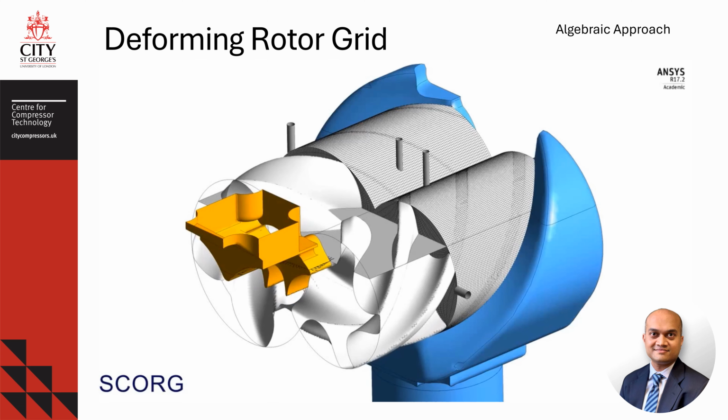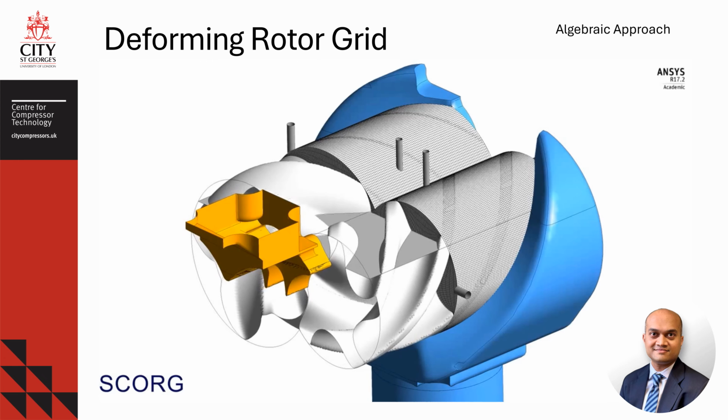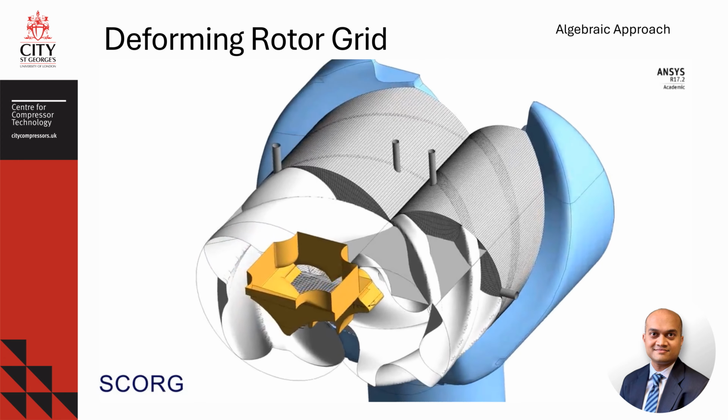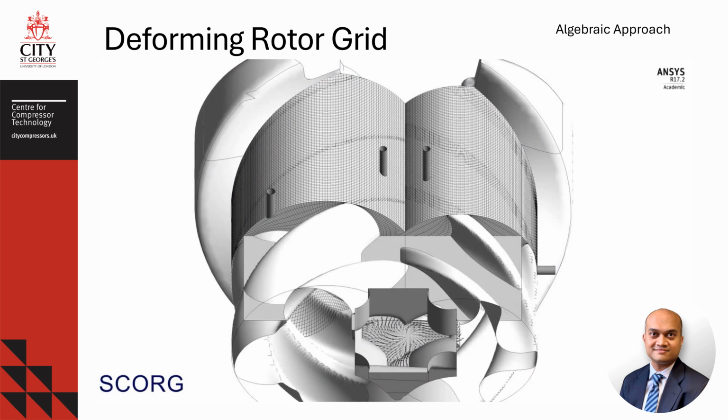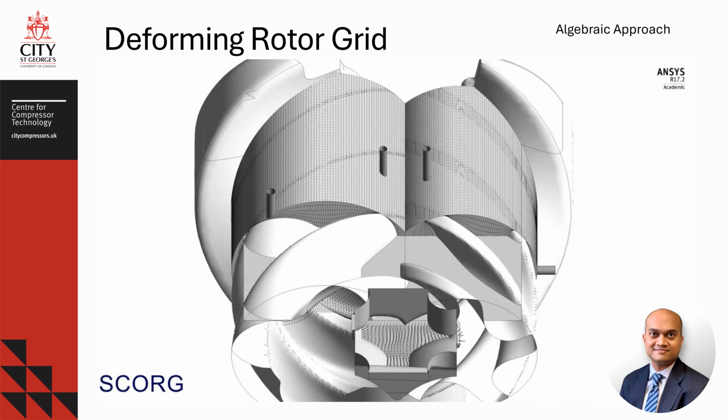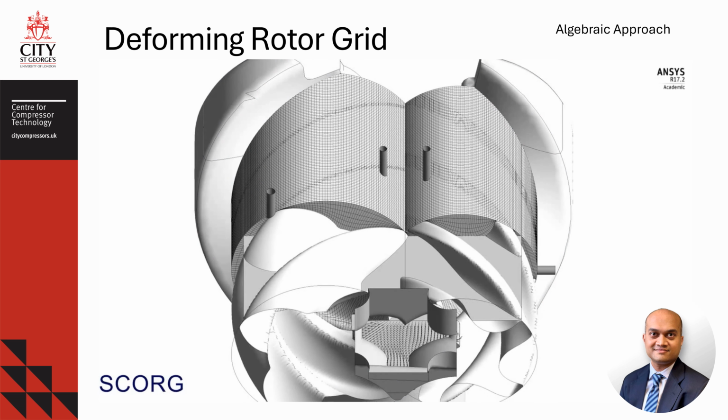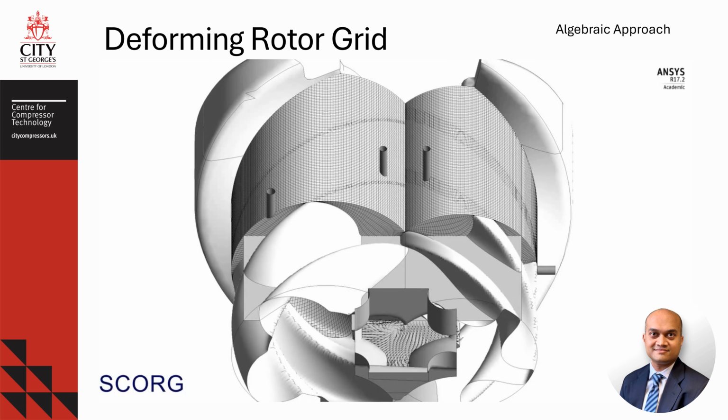The cell quality of the 2D mesh is then improved using a differential algorithm, and then it is assembled together to form the 3D mesh as seen here. The 3D mesh is purely hexahedral and consists of either two domains or a single domain based on the method used.